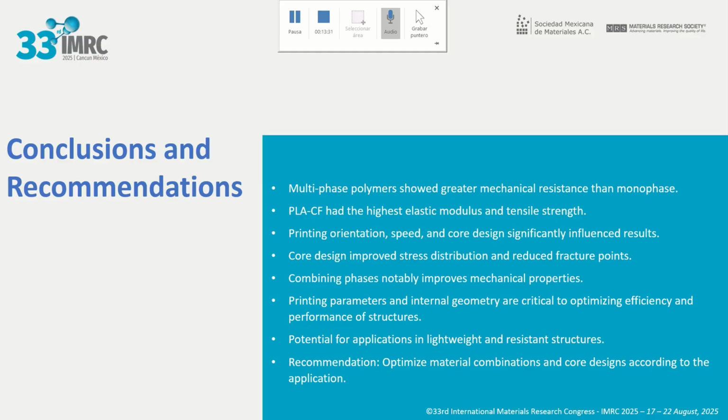Printing orientation, speed, and core design significantly influence the results. Core design improves stress distribution and reduces fracture points. The combination of mechanical properties, printing parameters, and internal geometry is critical for optimization, efficiency, and performance of structures. Potential for application in lightweight and resistant structures.